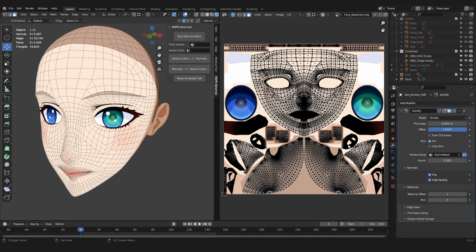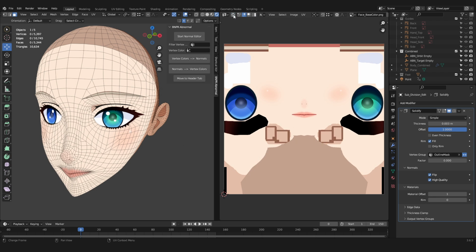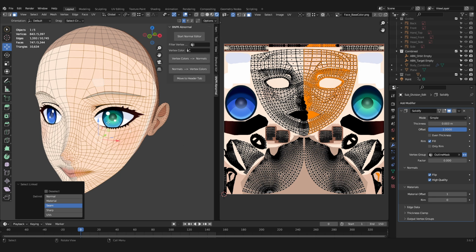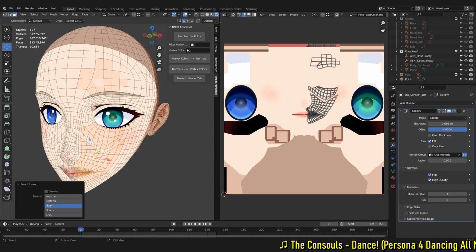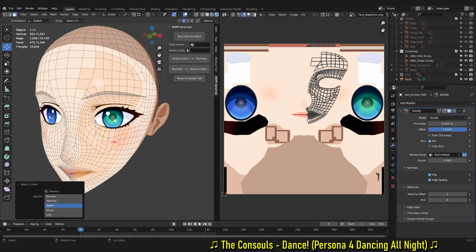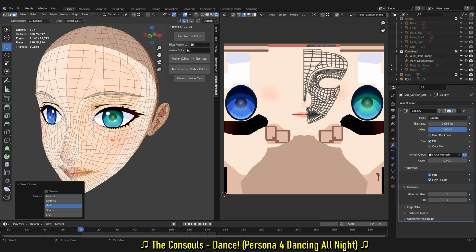Make sure UV sync option is unselected at the top. This option has a few quirks to it. Having it on allows you to select faces on the UV map, having them reflect in the 3D view. Having it off has the opposite effect. We only want to see the UVs we have selected in the 3D port, so it needs to be off.